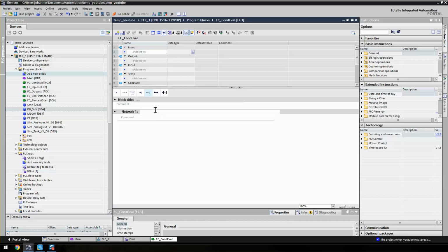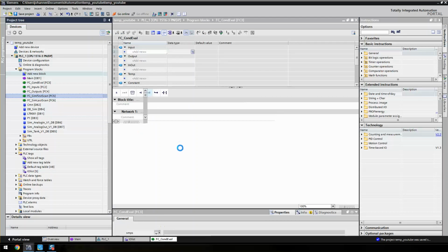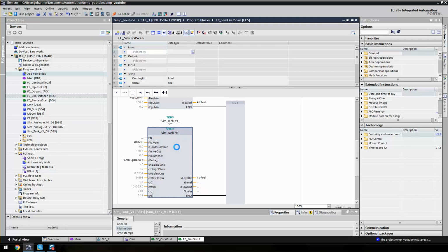Since we're controlling a water level in a tank, we have a level transmitter that gives us the water level, and we have an analog pump to control water flowing into the tank to fill the tank. We can improve our control by knowing how much flows out of it. And if you're into physics, that won't be too hard for you to figure out, but it is a constant times the square root of the water level, more or less. And you can check out Bernoulli or even just the simulator for that case on how that works.